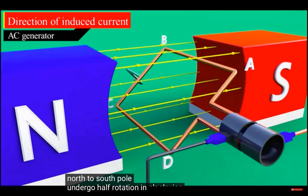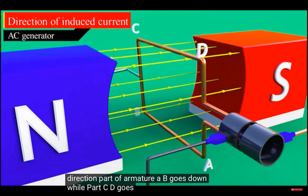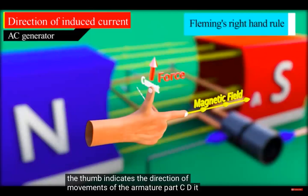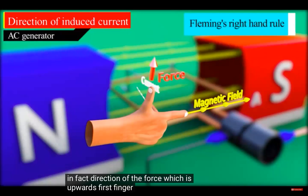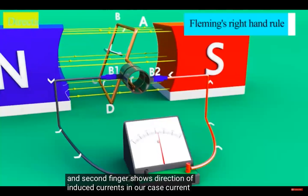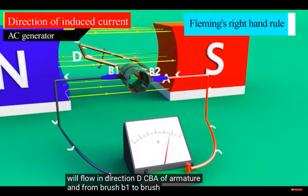Undergo half rotation in clockwise direction, part of armature AB goes down while part CD goes up. According to Fleming's right-hand rule, the thumb indicates the direction of movement of the armature part CD. It is in fact direction of the force, which is upwards. First finger points direction of magnetic field from north to south pole, and second finger shows direction of induced current. In our case, current will flow in direction DCBA of armature and from brush B1 to brush B2 through galvanometer.